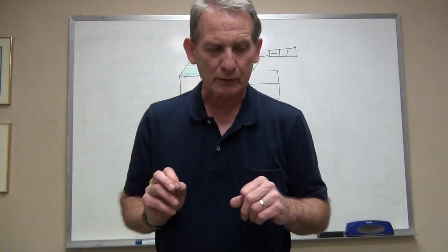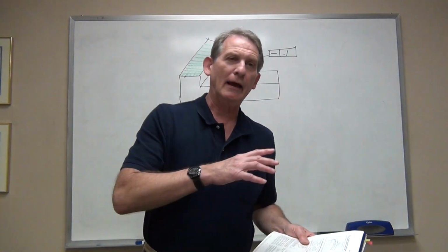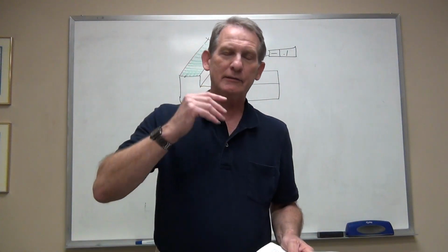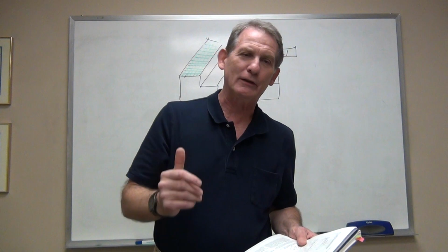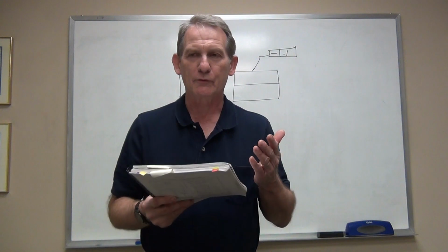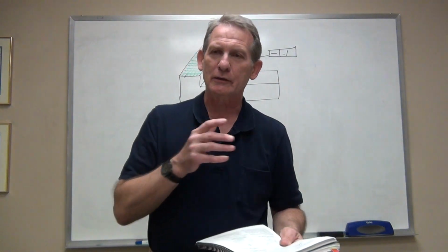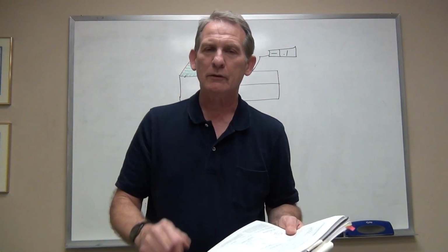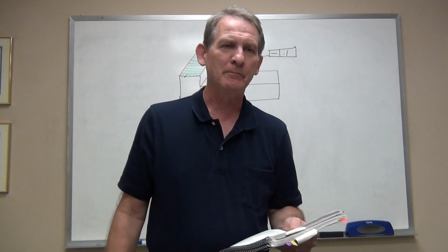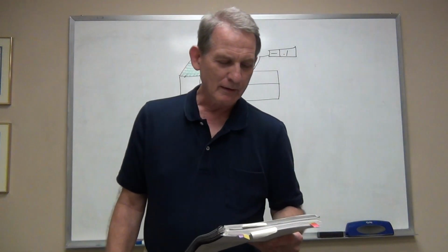Someone asked me, I think last time I taught this course, in figure 5.4 or 5.6, could that surface have been controlled, or should it have been controlled, with a flatness control? Yes, it probably could, or definitely could, and probably should have been. What they're showing is that if for some reason you have a part that preferentially wants to curl in one direction, you can control it by a linear control, and as long as that's okay, then you have a control that isn't going to cause you a lot of problems.